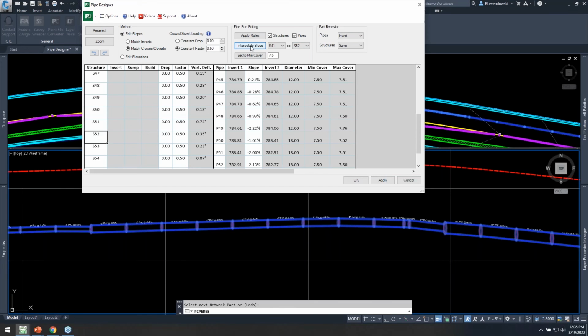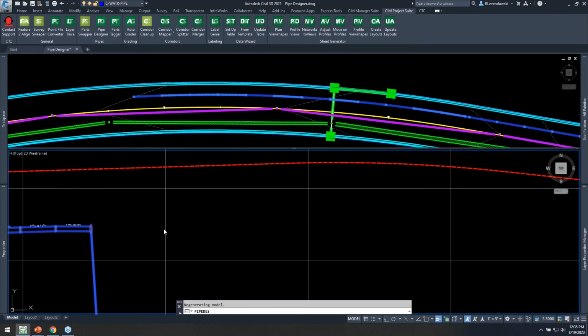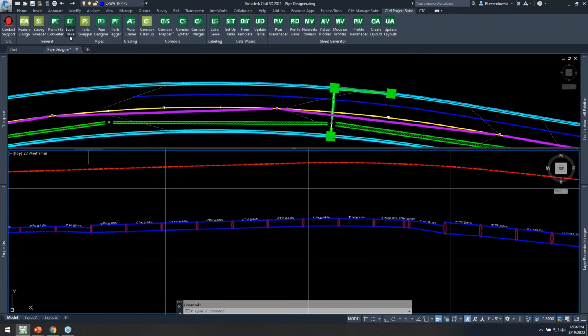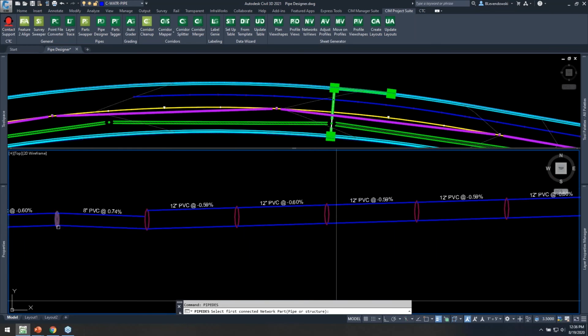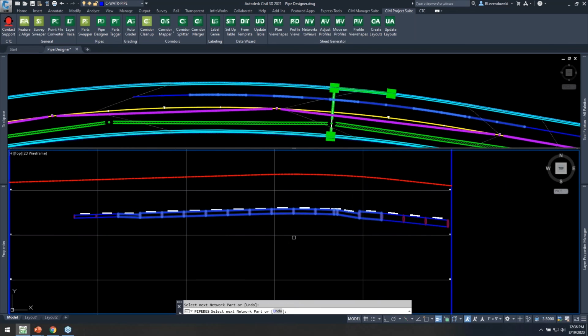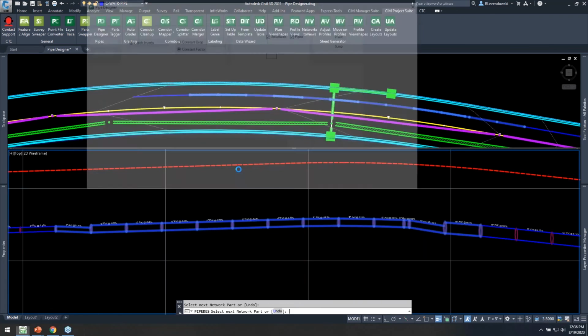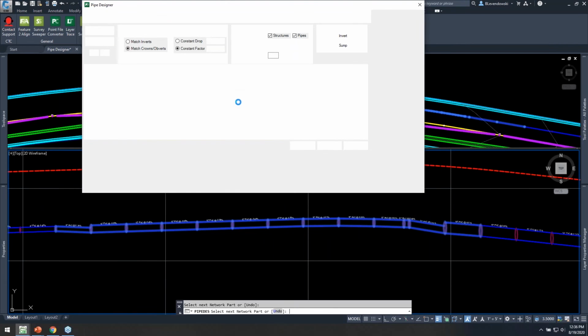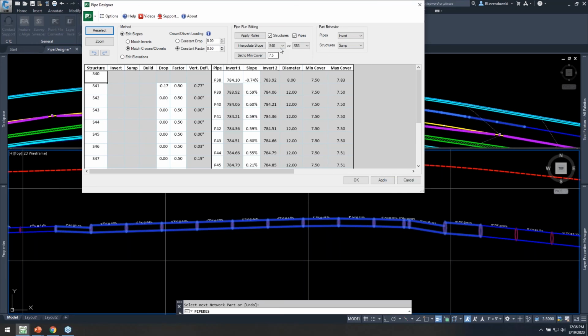Okay. Now if I interpolate slope, what you'll see is all those values calculated there. We'll hit OK, and then you'll see a constant grade across that area. Oops, messed up on something. Let's do that again. I'll just pick from here to here this time. Okay, we said we want to go from, let's set our cover again, make sure we have that appropriately.